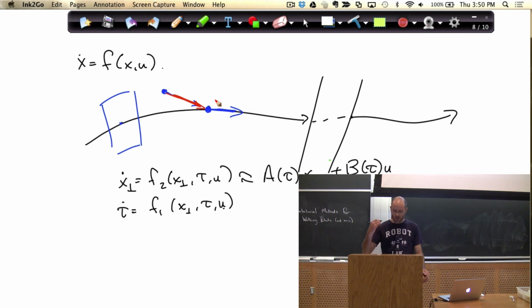You'd like to think, okay, there's an obvious solution to that. Let's just project down, and when I'm running the system, I'll remap time as I'm executing my time-varying linear controller, and I'll use that as my error. I've got my u equals K times x. Maybe if I just remap time as I'm going, that would be okay, but you actually can't do that. Sometimes you can get away with it, but there are simple examples where that will destabilize the system.